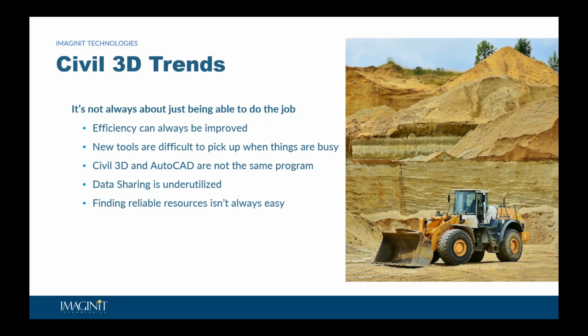And that tends to increase the chances of conflicts in design or conflicts in the data that's being shared there. Because if something is being copied from one file to another, if one of them changes or gets updated, you'll have to remember to update everything else. Versus if it's a data share with the XREF or data shortcut, synchronization tools are available that can synchronize all of the designs across the board because they're linked back to the same original data source. So that's always something that comes up in discussions as well.